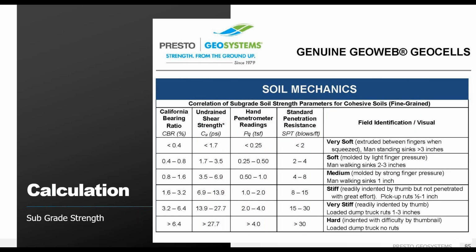A lot of these projects, we don't have the money or the time to do a full geotech evaluation or even field DCP tests. So this chart I have, if you're interested, I've handed out thousands of these over the last probably 15 years. What you can do, put it in your book bag if you're ever out on a job site. You need to design a road, a railroad, or anything, you can basically do a visual identification.